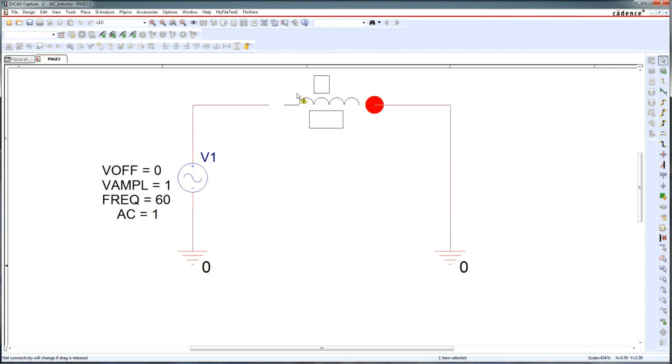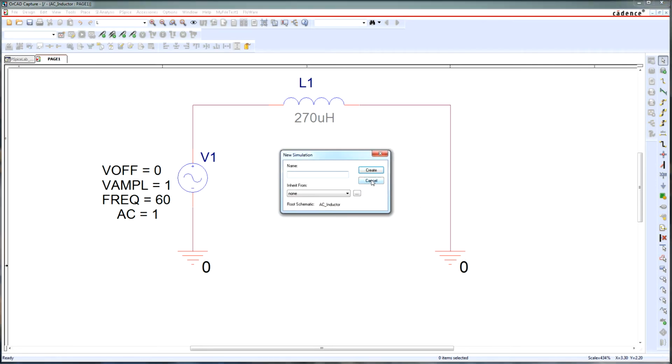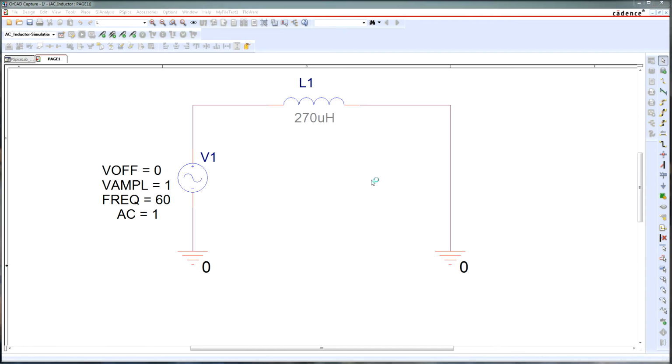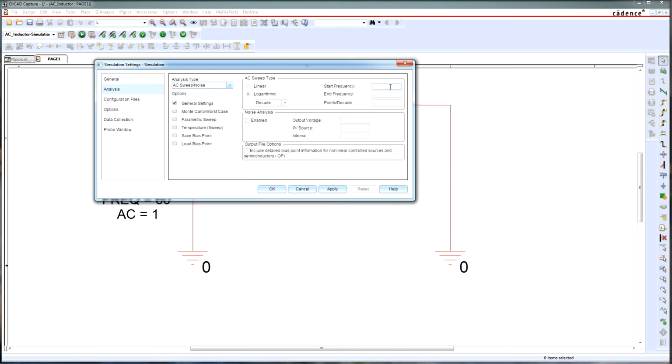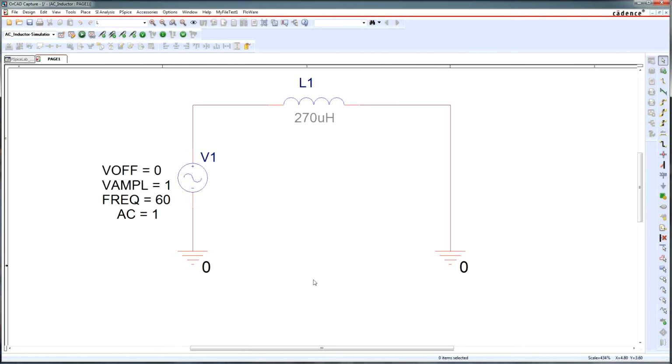That's why I clicked on Place. I have here my component, I save, and now let me make a simulation. So I'm going to make a frequency simulation where we say I want to start from 319 until 410 megahertz. I save and I simulate.